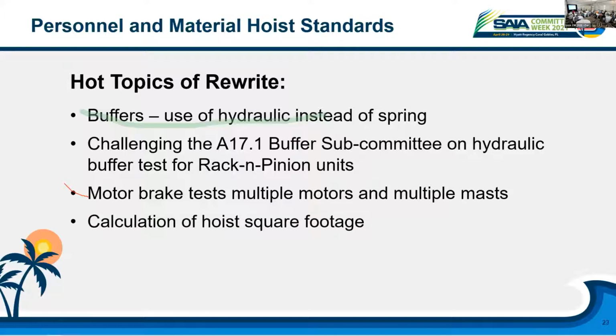And then calculation of hoist square footage. From 2007 to 2016, we had a change in the square footage calculation when it came to if you had a load cell, you can drop down to 82 pounds per square foot. And there was an interpretation that was written a while back on how to calculate that. But what happens is, where do we actually measure it? There's no defining terms of where we measure it. If you look at A17-1, where a lot of this came from, you have to measure it about 32, 36 inches up from the floor. That's where you measure your square footage. Or do you measure it to your doors or to the door seal?